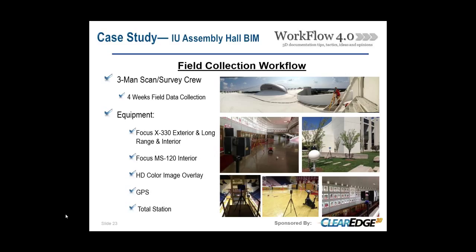So to tackle a project of this size, under these tight timelines, we approached this job using a 3-person crew. We utilized 2 laser scanners, both with 2 competent 3D scanning technicians with a lot of experience. We utilized a long-range X330 on the exterior. Then we utilized our Focus MS-120 to do the interior. And then the X330, we also used in short-range mode inside as well.